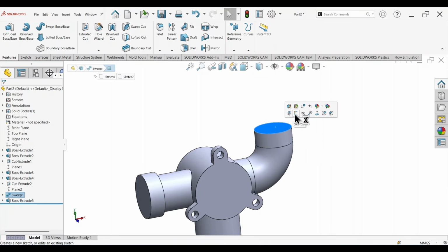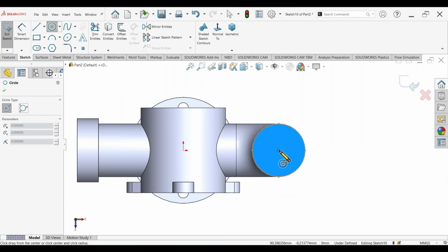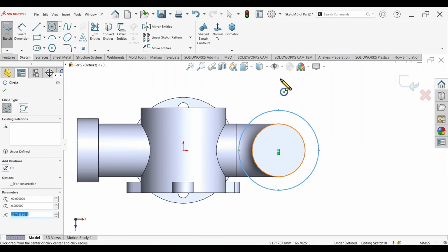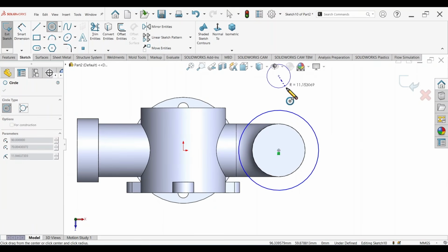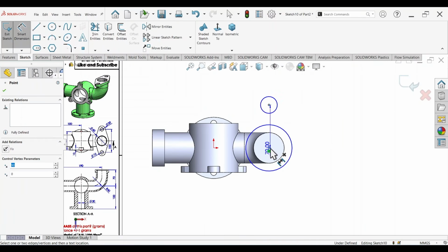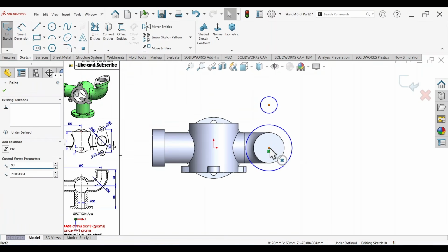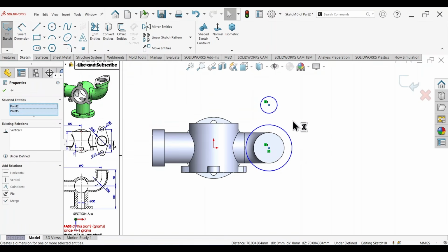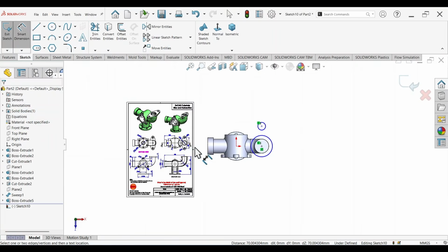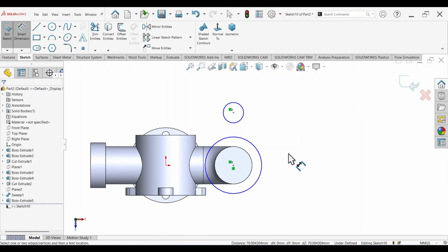All right. Now we're going to work on creating this flange here, the oval flange at the top. So select this top face, Sketch, draw a circle from this point here, another circle directly overhead. Set the relation between this point and this point as vertical. Smart Dimension tool, and if we look closely, we see that the diameter of the larger circle is 60 millimeters.